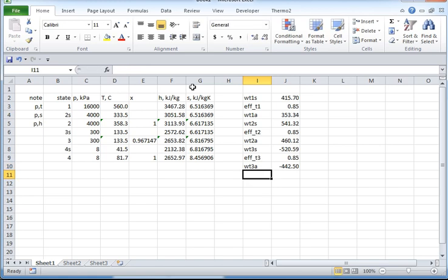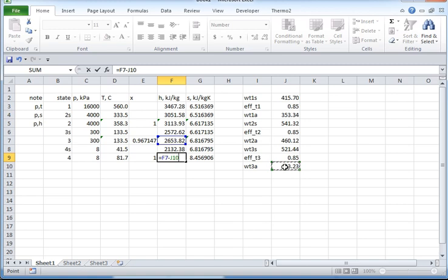I'll have to get rid of this equation, start again, and say the isentropic work for the third stage is from 3 to 4s. And then this is the actual work, it's the correct formula there. And so the enthalpy would be from 3 subtracting the work out of the actual third turbine stage. And there you go. And so you could take a look at the qualities.